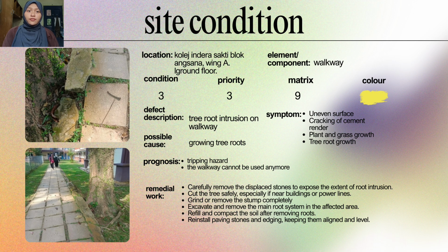Symptoms are uneven surface, cracking on cement render, plant and grass growth, tree root growth. Possible cause is growing tree roots. The prognosis is tripping hazard. The walkway cannot be used anymore.